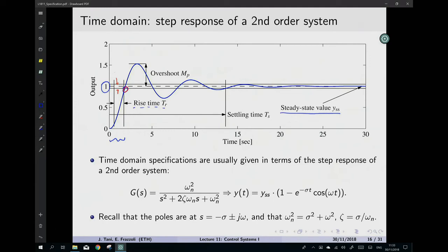So now we're entering a domain where there are approximations, and basically you'll find different definitions in every textbook you look at. But the rise time is defined as how long the system output takes to reach the reference signal for the first time. It doesn't mean it settles there, it just means it hits it. It's typically not a very important or meaningful time domain specification.